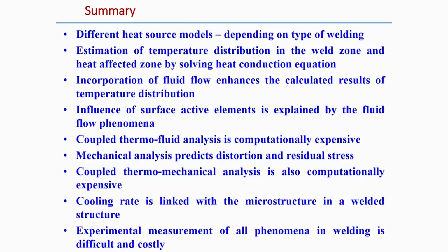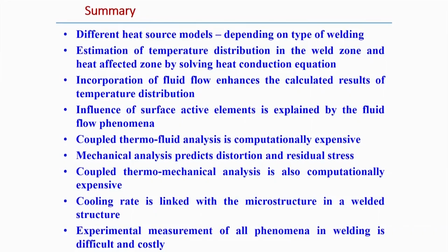Then mechanical analysis predicts the distortion and the residual stress, but mechanical analysis needs the temperature distribution as an input to predict the distortion and residual stress in the welding process. Then of course, coupled thermomechanical analysis is also computationally very expensive.